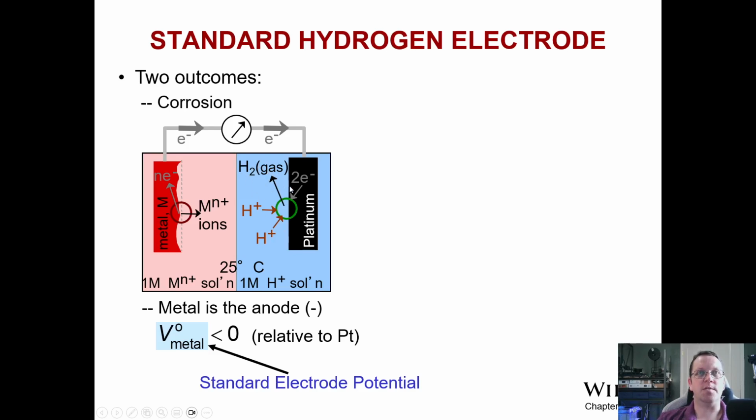So hydrogen gas is forming as these electrons are reaching the surface. There's really not as much happening to the platinum, but this sacrificial metal is eroding. And that's a technique that we use for corrosion control later on, by reversing the flow of electrons and forcing this to take place.